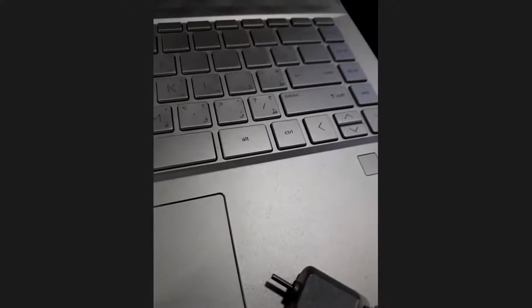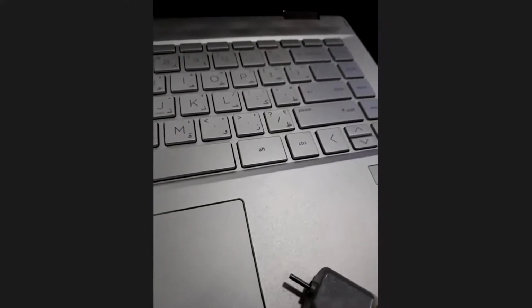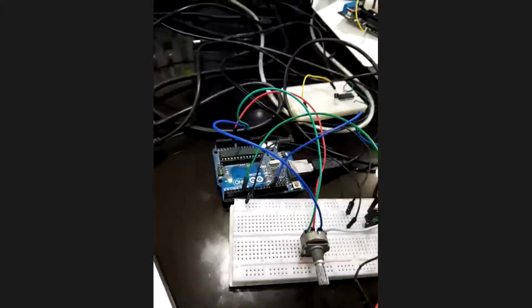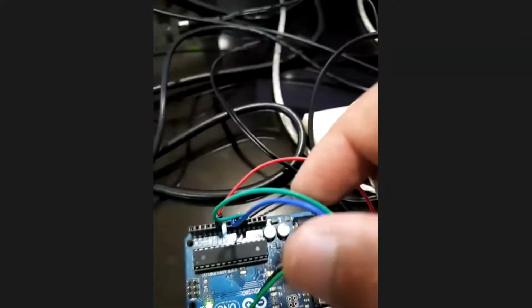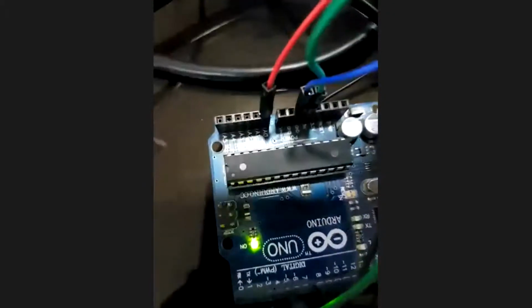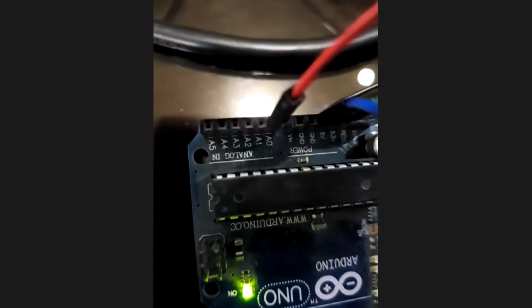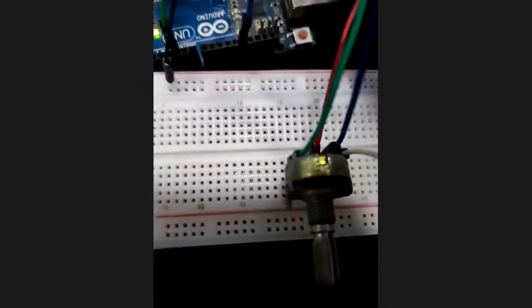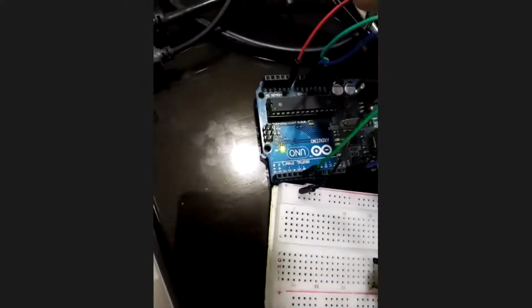I'm going to go back to our drawing on the screen. A voltage divider, basically. So when I turn, I change the voltage. I connect it to an analog read pin. See these pins, the green and blue. If you see my board, they're connected to 5 volts and ground. Then here A0, the red line, comes from the middle connector of the potentiometer, which is the analog voltage.